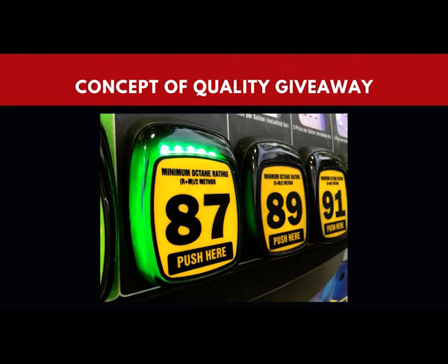So, if for any reason you give excess quality, then it means it is eating the profitability of your business. This concept is known as quality giveaway. Sometimes the refineries will give excess quality because they may not have time to do a reblend and then resampling, because a tanker may be waiting in the port to take the load of a particular consignment.